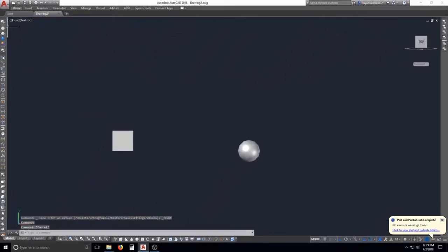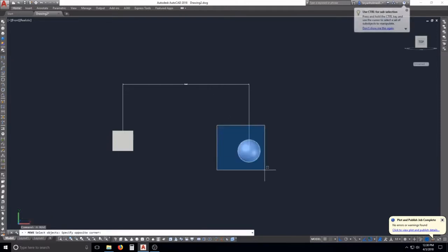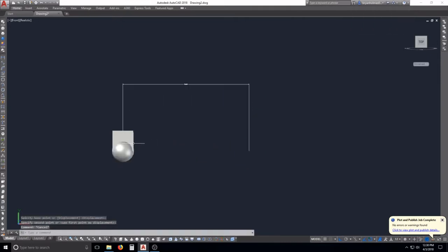Now what we're going to do is use our dimension, and we're going to snap from the center point to the center point, or center point to midpoint in this case. And then do not grab the geometry when you move stuff, because you don't know where about it you're grabbing. Grab the dimension line, because it's on a flat plane. That's why it's an important tool in your 3D modeling. So we're going to move it, M, enter, and then move it to the perpendicular. Okay, cool deal. Now we can look at it from the side.